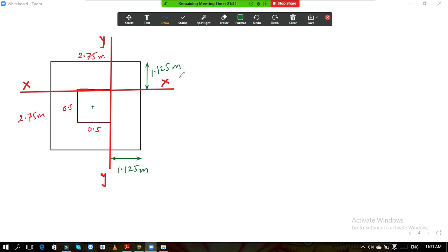Okay. So now, bending moment. What is the formula for bending moment? For the footing, the formula for bending moment is equal to WL square by 2. So what we need to do now? We know the value of L. We know 2 is the constant. We need to find out the value of W.